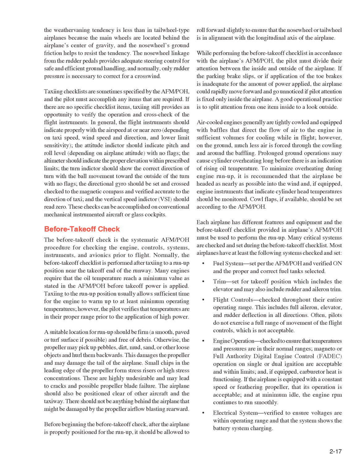Before takeoff check. The before takeoff check is the systematic AFM/POH procedure for checking the engine, controls, systems, instruments, and avionics prior to flight. Normally, the before takeoff checklist is performed after taxiing to a run-up position near the takeoff end of the runway. Many engines require that the oil temperature reach a minimum value as stated in the AFM/POH before takeoff power is applied. Taxiing to the run-up position usually allows sufficient time for the engine to warm up to at least minimum operating temperatures. However, the pilot verifies that temperatures are in their proper range prior to the application of high power.